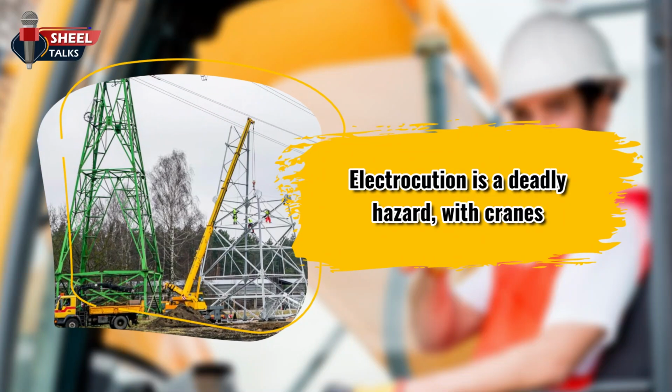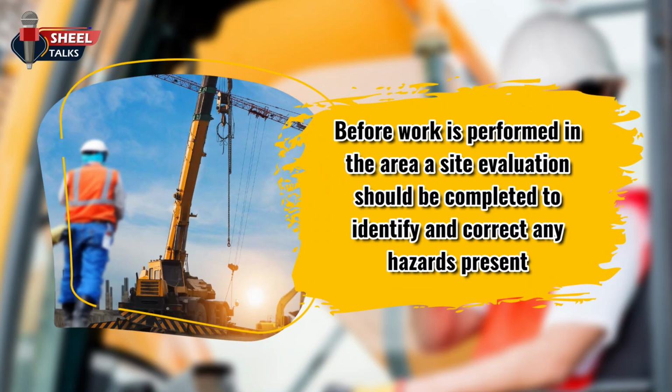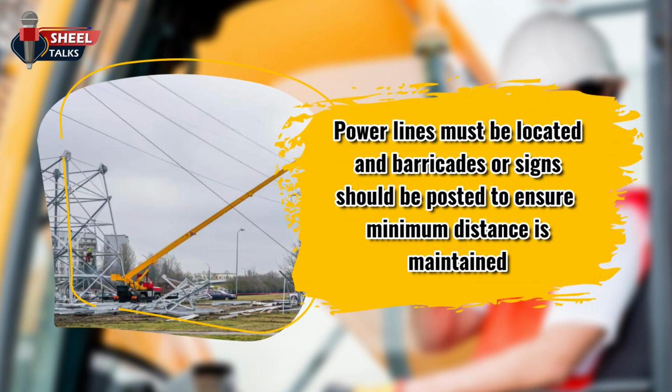Electrocution is a deadly hazard with cranes. Before work is performed in the area, a site evaluation should be completed to identify and correct any hazards present. Power lines must be located, and barricades or signs should be posted to ensure minimum distance is maintained.